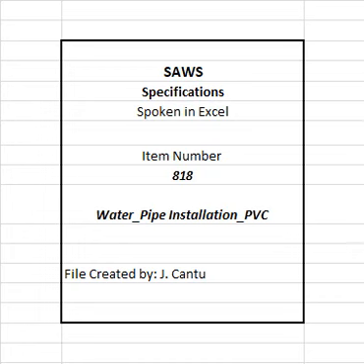C. Details of all piping systems components confirming that the pipe and fittings conform to the specified requirements. D. The contractor shall submit shop drawings of pipe, fittings, gaskets, hardware, flanges, appurtenances, special details sufficient to demonstrate compliance with these specifications and applicable pipe installation specification. E. Fabrication drawings showing 1. Wall thickness. 2. Pipe length. 3. Pipe joint.